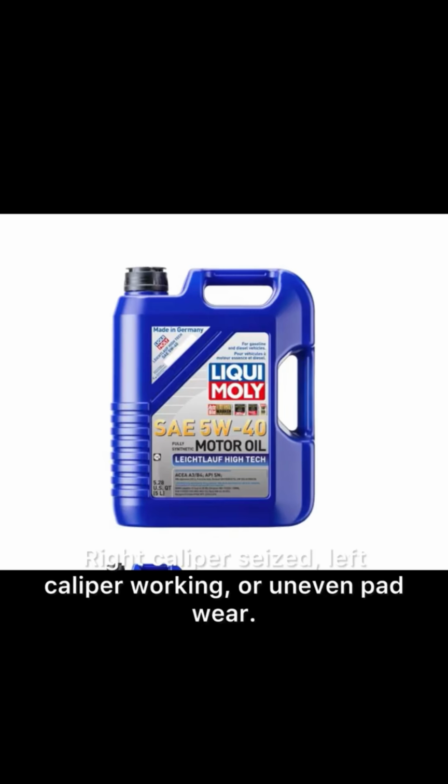Squealing noise when braking lightly. Cause: worn brake pads, glazed rotors, or missing anti-squeal shims.